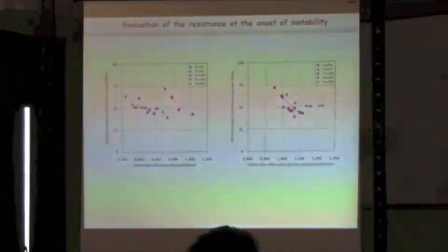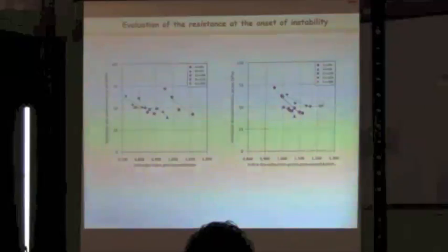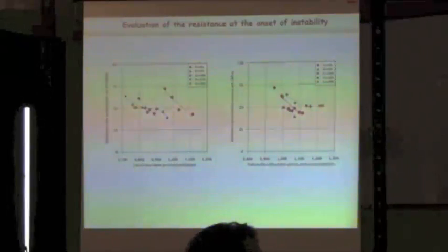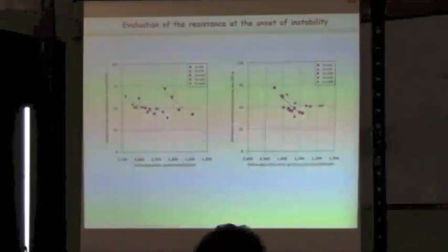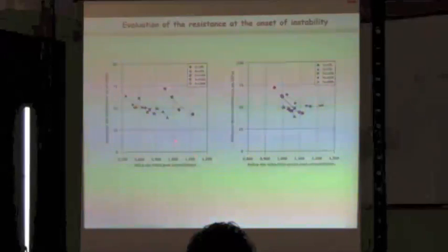This point is very important because usually in the literature it was shown that below the threshold fine content, the fines don't play any role and are inactive. But this research shows that even below the threshold fine content, which here is 20%, the fines start to participate in the force chains.